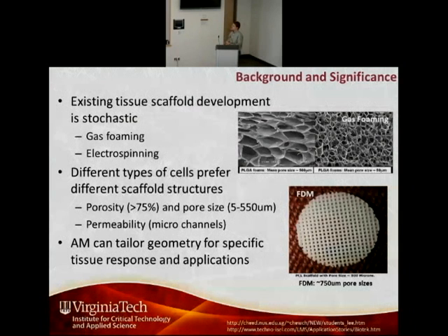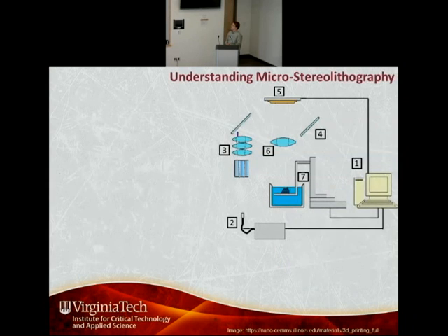So basically, here are the details of how this all works. Again, these are the actual micro mirrors. The mirrors themselves are 10 microns, so each is equivalent to a pixel on your bitmap. You turn that on and off, which means they just move the mirror in or out of the light path. And that allows me to dynamically generate masks. And we can reduce that projected image quite a bit, with some very small feature sizes.